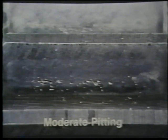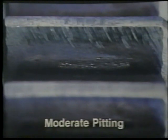As with gears that show frosting or initial pitting, this type of moderate pitting will not cause a noise complaint because the overall involute or curved form of the tooth has not been affected. This gear also has pitting on approximately 50% of the tooth surface, but unlike the previous gear shown, this gear should be replaced.